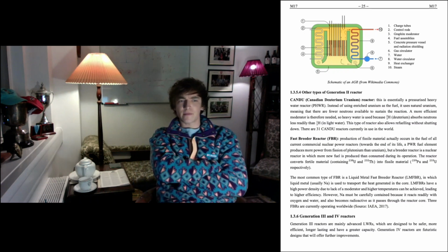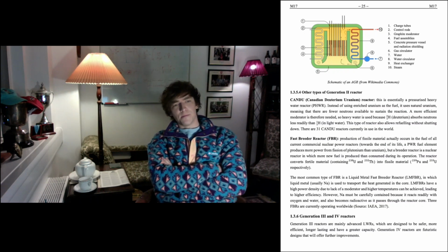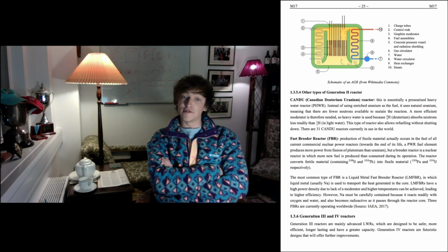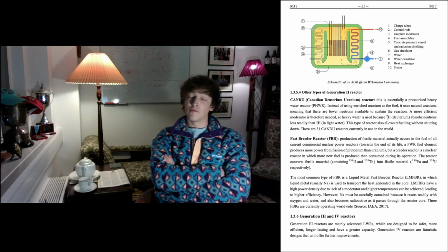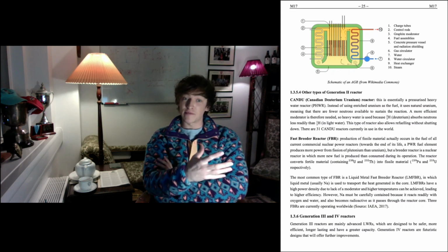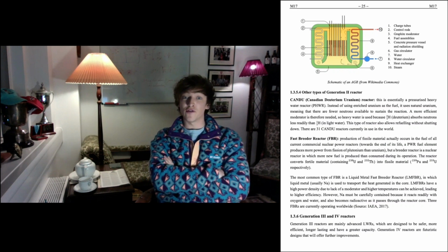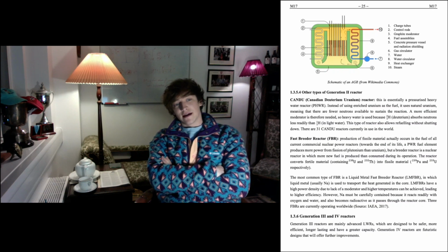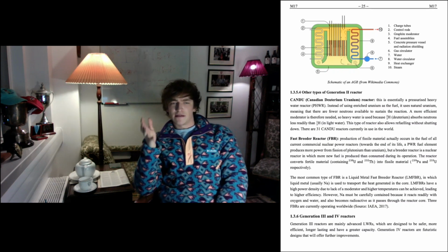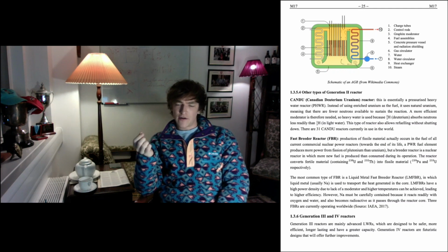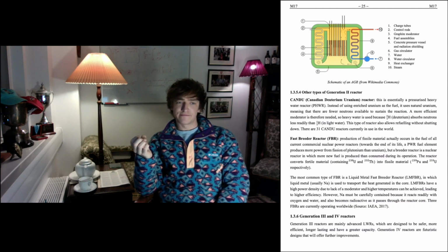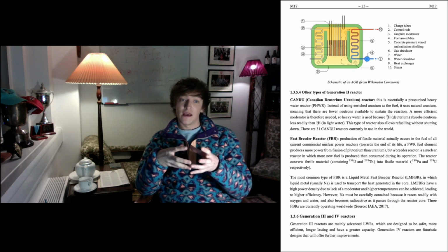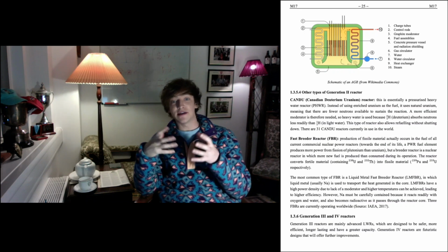Although it is worth noting that most commercial thermal reactors produce more power, in fact, from plutonium fission than uranium when they're at the end of their lives, because you've produced all that plutonium, so that's the main fissile fuel that you're burning up. Now, fast breeder reactors most commonly use a liquid metal coolant and have a much higher power density due to the lack of moderator, meaning you can pack more fuel into a smaller space, with higher temperatures being reached, producing better efficiency.